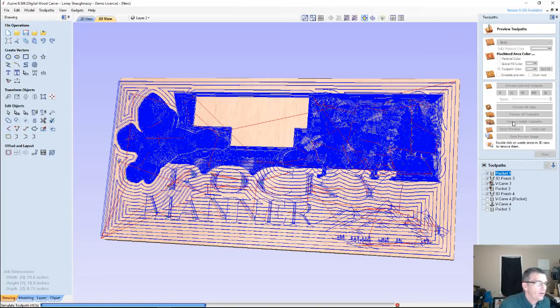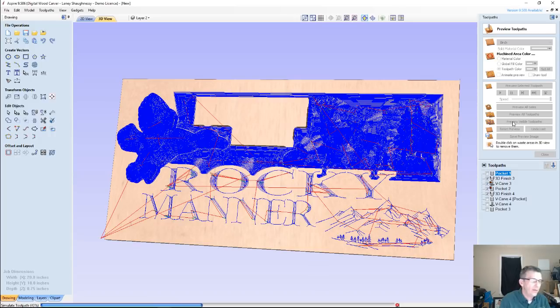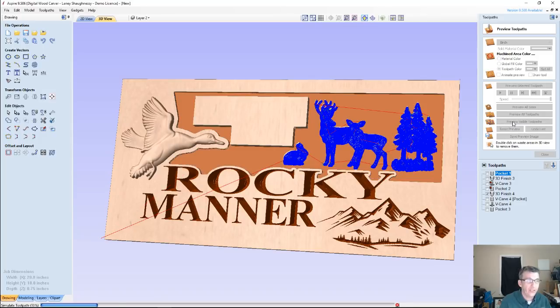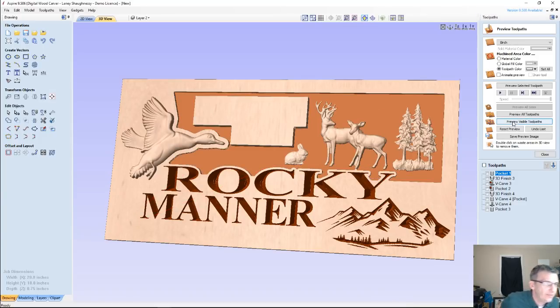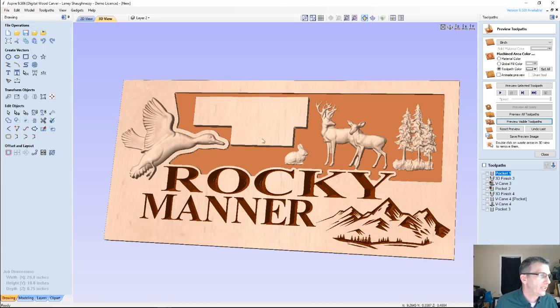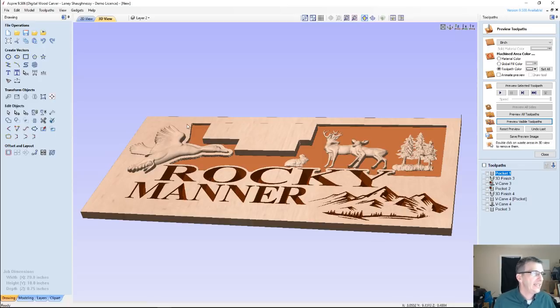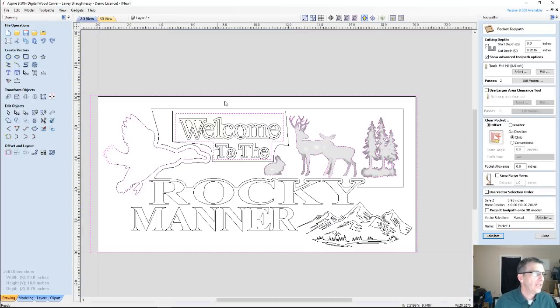Man, that was crazy. Okay, we're almost done. What I had to do was, because we're working with two different levels, starting from 0 at one point, or down 1/8 of an inch for the other models, this raised text is essentially both worlds. If we look at this from the side, with the tilt, you can see that when the first pocket cut got cut, it didn't include this area here, and I actually want it to. So for this first pocket cut, this vector gets taken out of the equation.